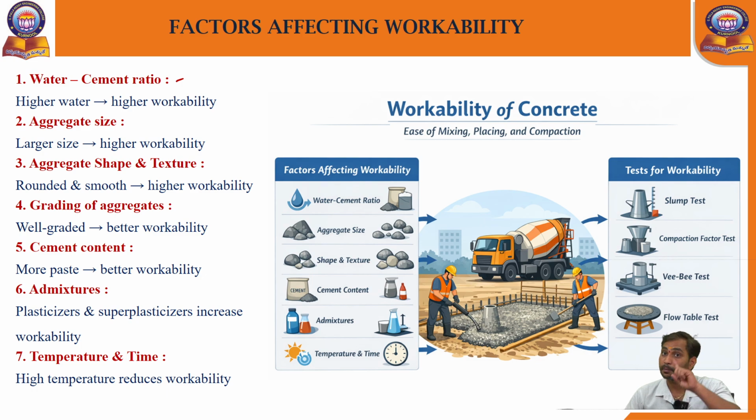In the previous lectures we have discussed cement. If the cement is available in one shop at a very low price, can we purchase it? No, we should not purchase directly. We have to check the expiry date, how many days or months ago it was manufactured. Best before 3 months or best before 2 months, like that we have to see. And next, the sizes and properties, everything for the cement, same as for admixtures.